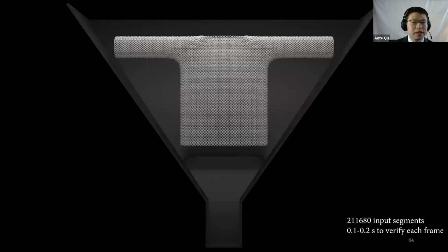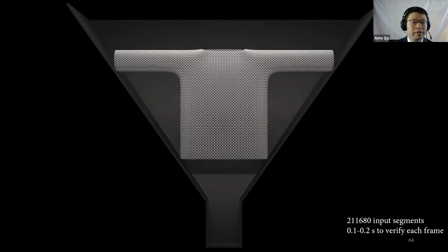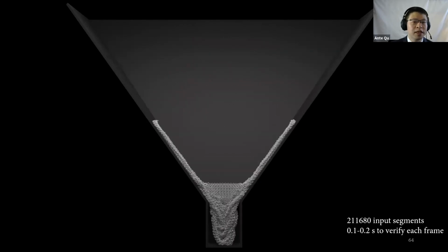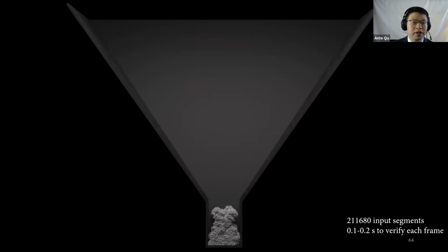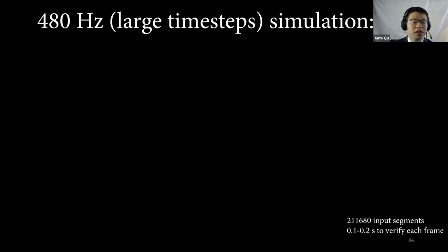And so here are some example results. In this example, we pack a Kusari chainmail shirt of curved rings into a box for 3D printing. It has rigid curved rings, which we simulate with Bullet in Houdini. The simulation takes 15 minutes to complete. We will first use large time steps, which can miss collisions, and then show smaller time step sizes.